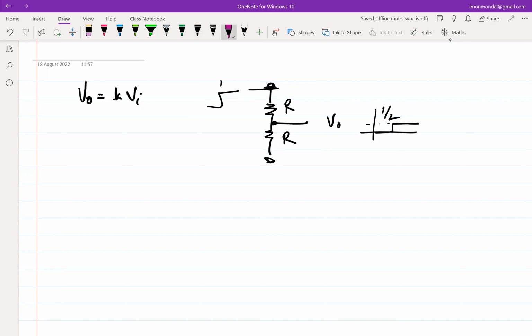However, if we just put a capacitor here, inadvertently, because capacitors cannot be neglected, what will eventually happen is that this step will not be as sharp. There will be some profile to it. Essentially it will settle to wherever it needs to, but it will settle after some time. So you can think of it in such a way that the capacitor to some extent delays the steady state, right? Whatever the steady state we want to reach, the effect of capacitance is essentially to delay it. Now, how it delays depends on how the capacitor is connected, whether it is connected in parallel, series, and those considerations. As it turns out, if you connect capacitors in certain circuits in a certain way, it can also advance your input, advance the output. But those are the things that we will see later.